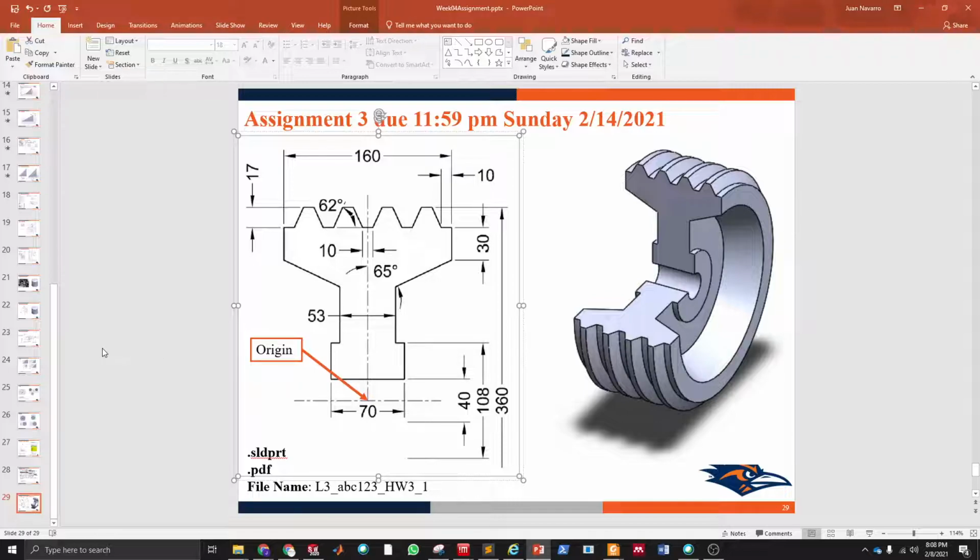So I don't think it has any other complication. Just the total diameter of the entire pulley is 360 millimeters. As you see, this arrow goes, but then it's cut here. This means that it's an entire diameter. And the same for these 40 and 108.